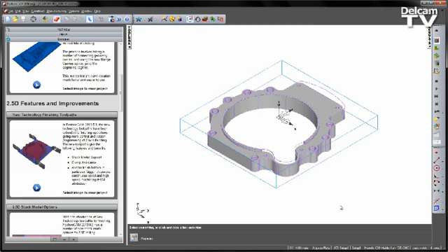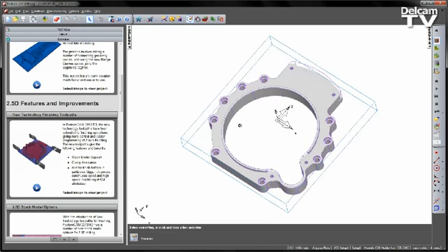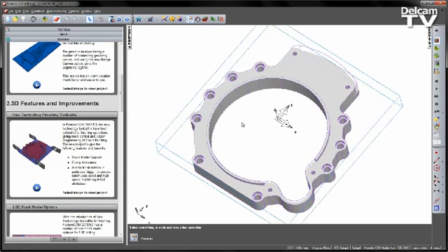The new toolpaths give a number of benefits, including stop model support, clamp avoidance, and, if using the finished bottom in particular, bigger stepovers, continuous spiral, and also high-speed machining options. In this example we have an adapter plate, and we're going to look at some of these finishing operations, with the exception of the stop model support, which is covered in a later video.